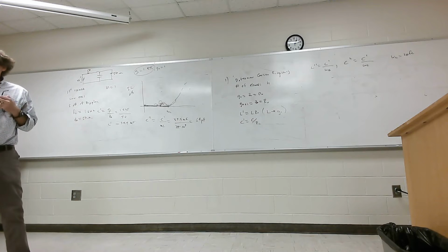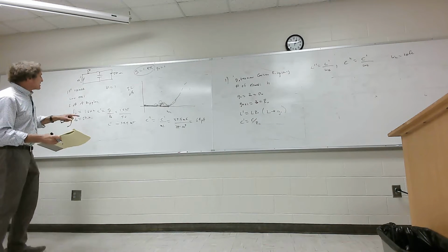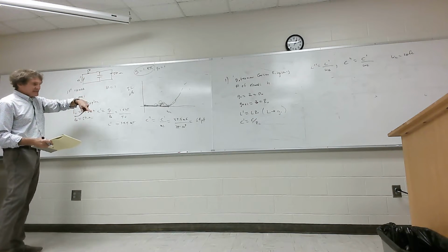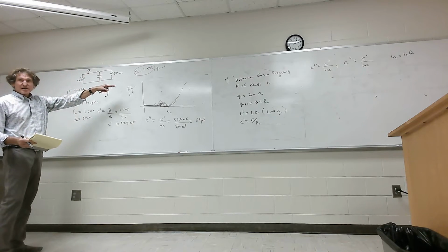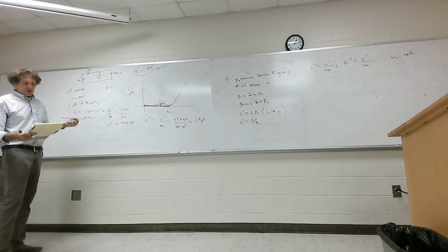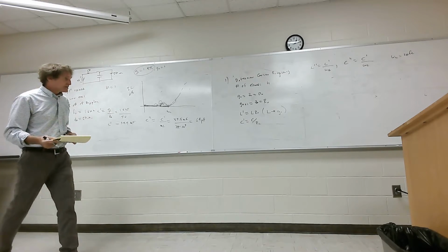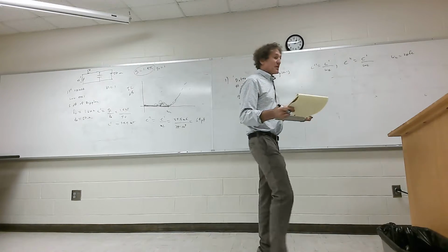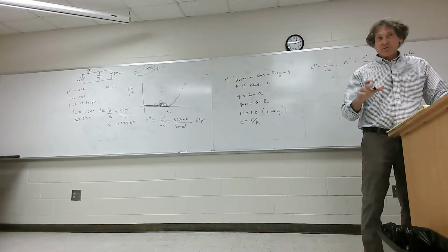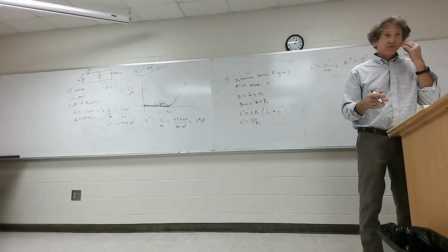Now, if you actually, you guys use SPICE, right? LTspice or any of that stuff. If you actually build this circuit, put 50 ohms there, make that the capacitor, 50 ohms there, and then you did a frequency sweep, and look at the insertion loss, you're going to see you get exactly those values. 3 dB of ripple, everything, it's precise. The only thing I'm doing though is looking at values from a table. Very little true mathematics, just using tables.